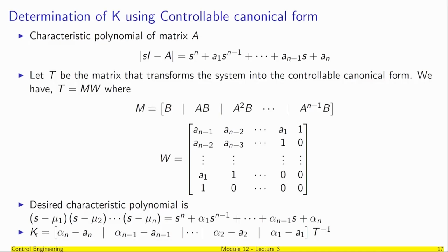So, what we have seen in this lecture is the definition of controllability to check if the system is completely controllable or not, and if the system is completely controllable, how exactly to design the control law. The only control technique which we have learnt here is what is called pole placement. There are other formulas, typically called Ackermann's formula.